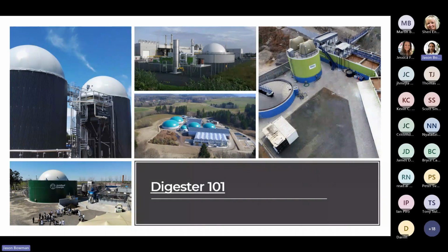There is a reason for this, which is that not all waste is created equal. Different industries produce waste or wastewaters with different chemical and organic makeups. You've probably heard me talk about this at length in some of the other webinars that we've done. But we find that different forms or different volumetric rates are required based on how the bacteria are going to react to the incoming feed.